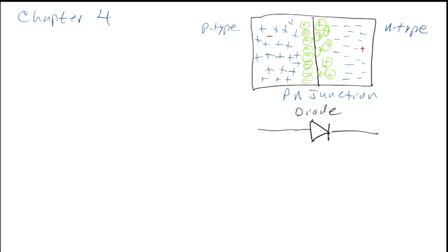And this explicitly means that this side of the triangle corresponds to the p-type region, and this line here, where the triangle is coming in, corresponds to the n-type region. So when you see a diode, it may have a symbol like that printed on the package.